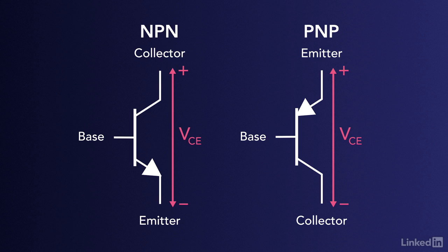Now, I have a hard time remembering which symbol is the PNP and which is NPN, so to keep things straight, I like to use the mnemonic "not pointing in" to remember that the arrow on an NPN transistor is pointing away from the bar. It's a slightly odd-sounding negated statement, but it works. I don't have a similar mnemonic to describe the PNP, so if the "not pointing in" statement doesn't apply, you're looking at a PNP.